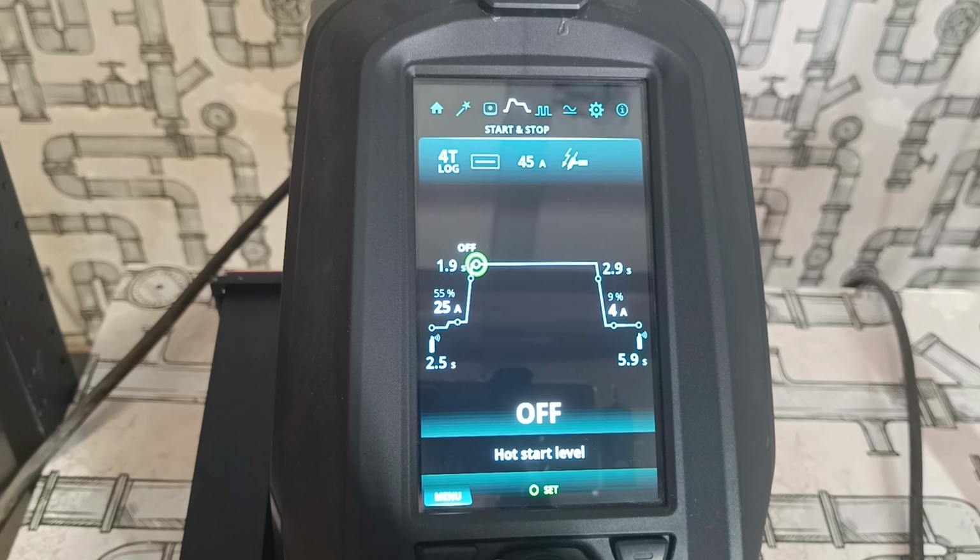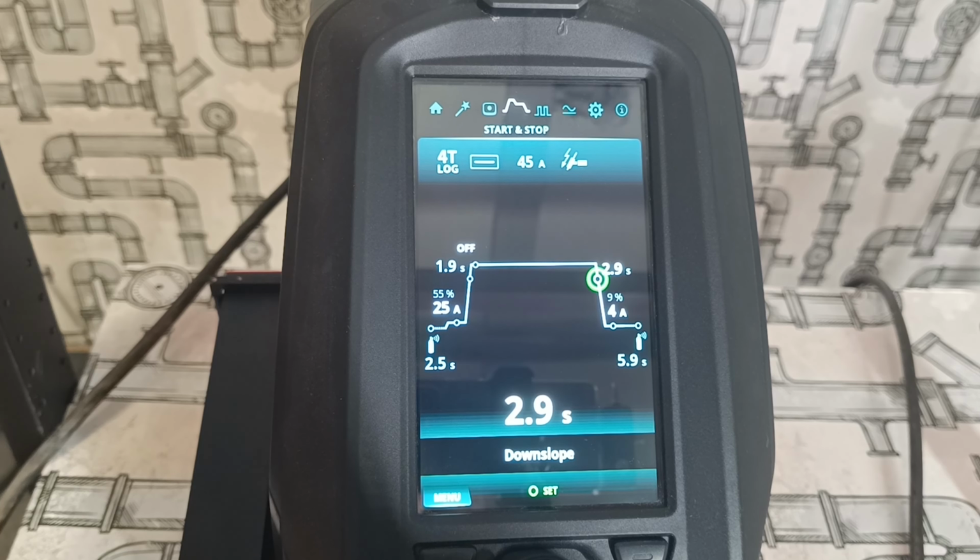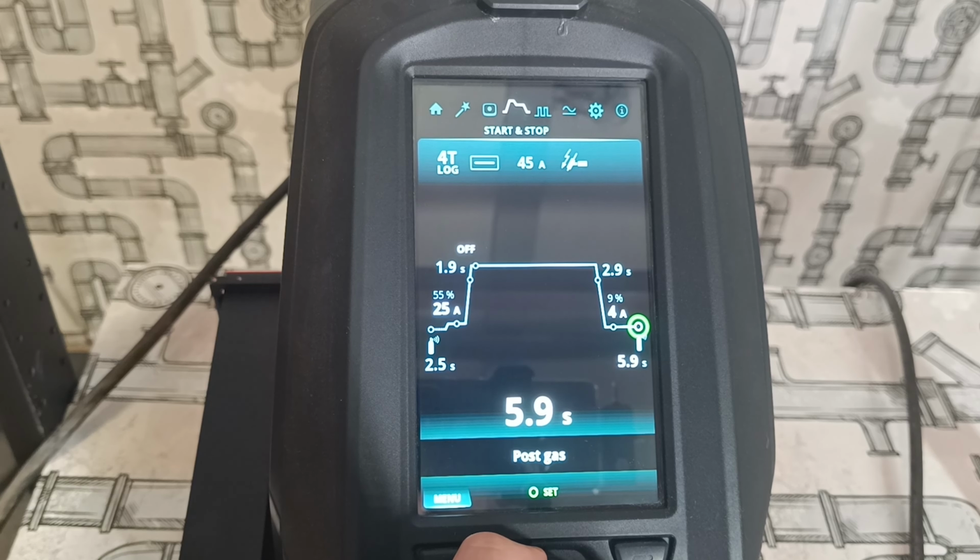Once we set those settings in place, we only need to set the rundown parameters. The current rundown time is the time during which the welding current decreases to the final current, which we can also set. The current rundown time and the stop welding impulse always match. The last parameter we need to set is the gas post-flow time, which provides gas protection after the welding.